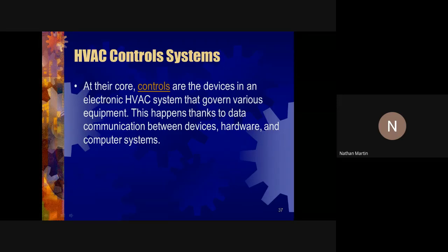So when you come into a big area, it's a central unit. Even the supermarkets do it nowadays. Rather than carrying ducts everywhere, most of them will refurbish, duct just to the general area where the food is with the central unit, and in the office spaces where you have the account staff, the managers and so forth, they use split units. All right, so this is how they use a combination of the two types of units to make the system more efficient. Because at the end of the day, they are going to save.